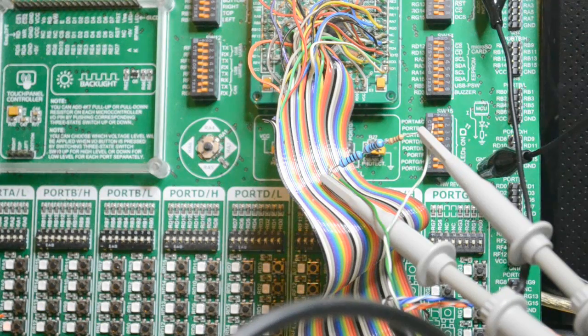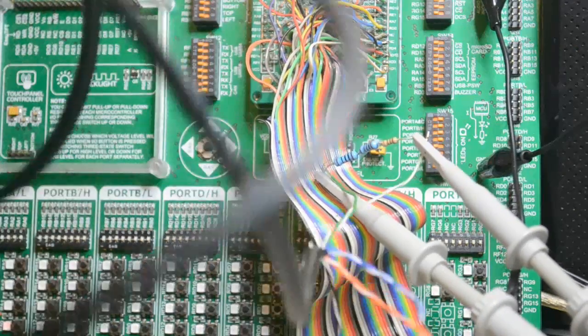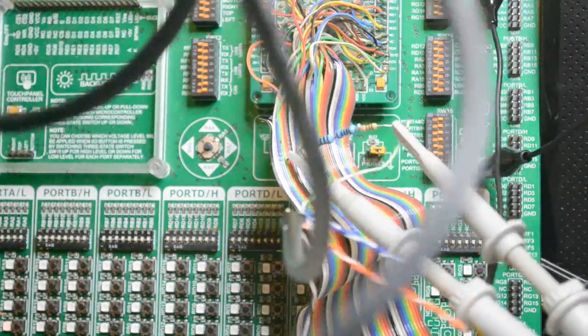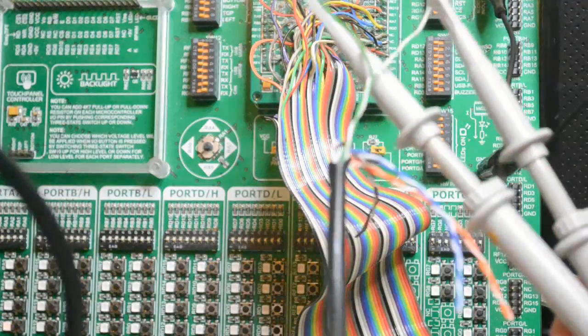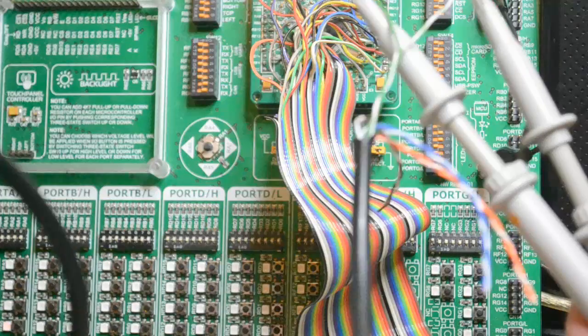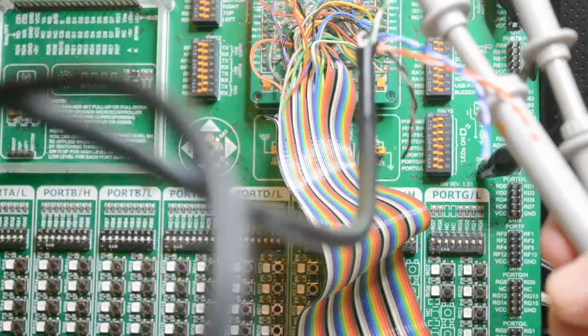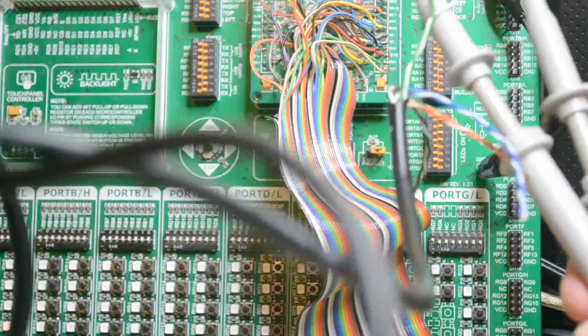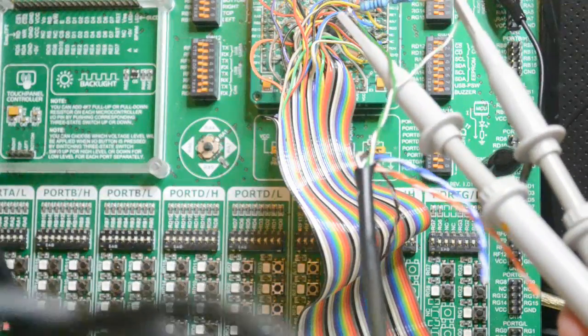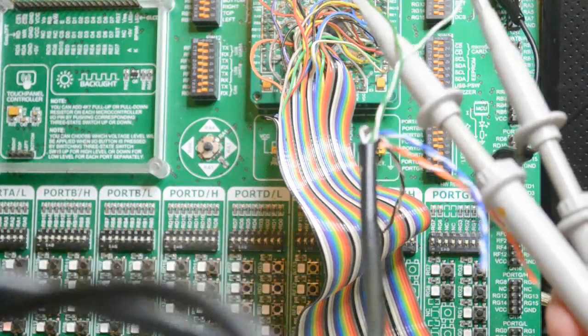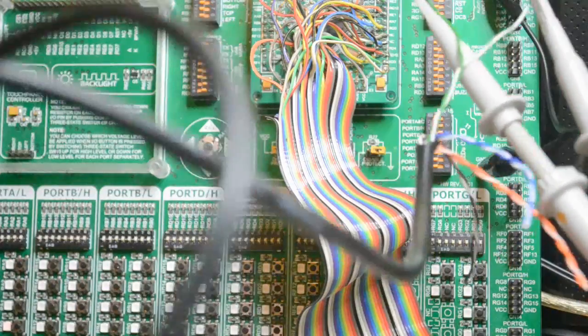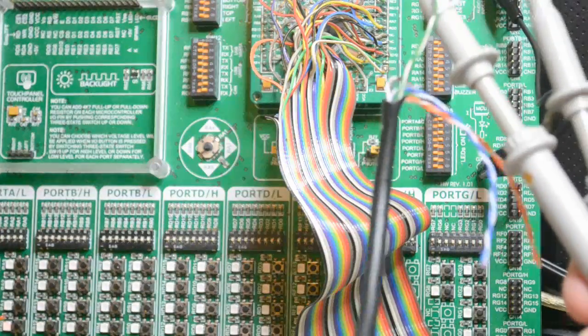Because I haven't got a CAN receiver or transceiver set up at the end of this wire, I've just got a simple 120 ohm resistor, or a couple of resistors to make up 120 ohm. Now in this instance, that 120 ohms isn't quite right, it's overloading the CAN line, but it just illustrates what you're meant to do. 120 ohm termination resistor at the beginning and the end of the CAN line.